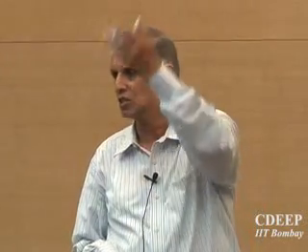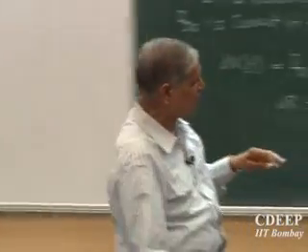So L may be very small, and W can be reduced as well. So the ratio can still be maintained at whatever value I want: 4, 8, 16, 32. Generally these will be the values. W by L will typically be 4, 8, 16, 32, 64. Why? These numbers are binaries, powers of 2. Generally, this is essential because when I make designs on a computer, it is much easier to double the lengths every time. If I make a unit, I just double it, double it. So all the numbers will always go 2, 4, 8, 16, 32. This is just for those who will become designers later.